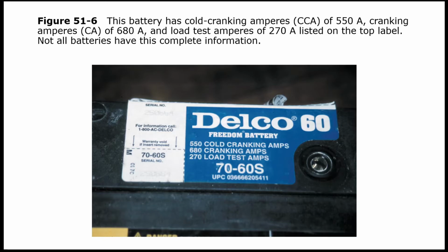So 680 amps and a low temperature test. The load test amperes of 270 are listed on the label. So for example, right here, cold cranking amps 680. Load test amps, they don't normally give this to you. That's a given right there.